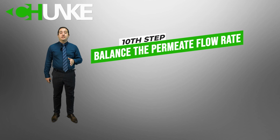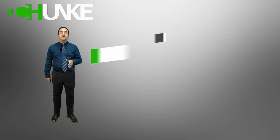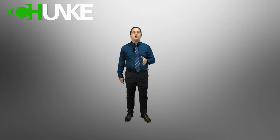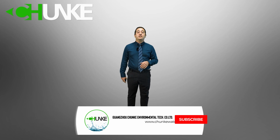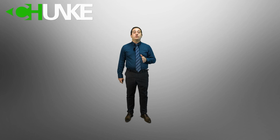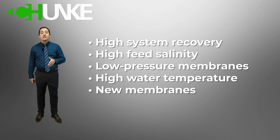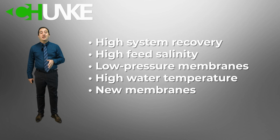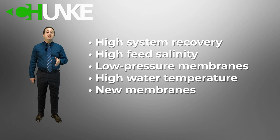10. Balance the permeate flow rate. The permeate flow rate of the last module of a system is normally lower than the flow rate of the first element. This is a result of the pressure drop in the feed channel and the increase of the osmotic pressure from the feed to the concentrate. Under certain conditions, the ratio of the permeate flow rate of the first element and the last element can become very high. These conditions are high system recovery, high feed salinity, low pressure membranes, high water temperature, and new membranes.